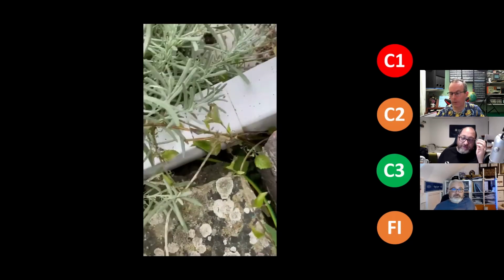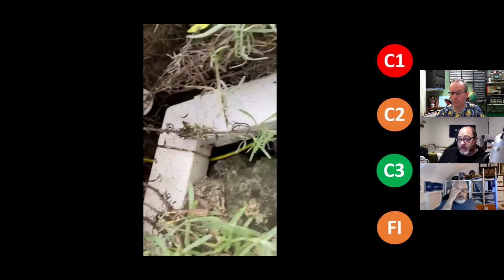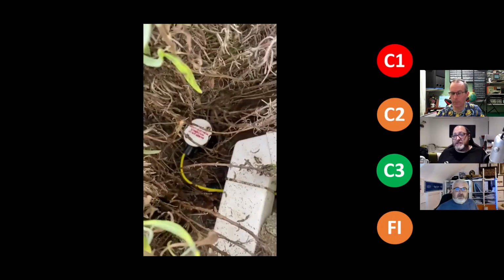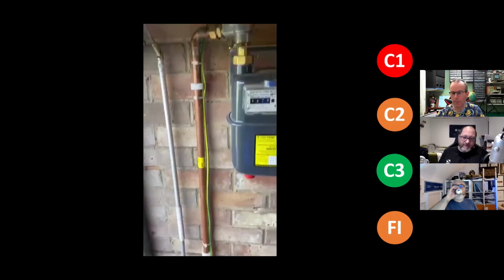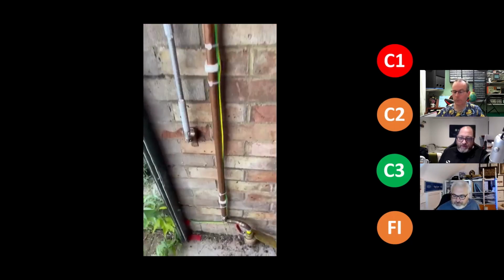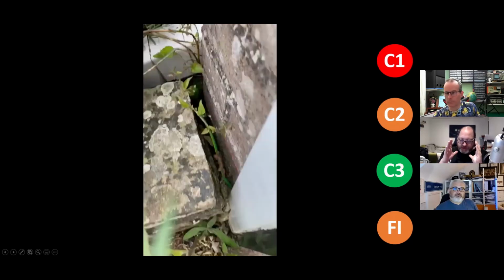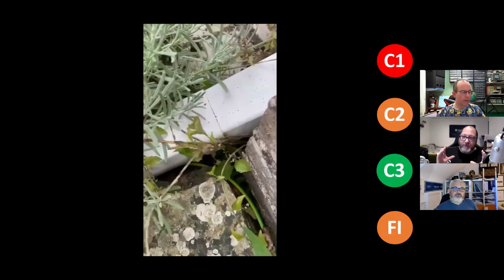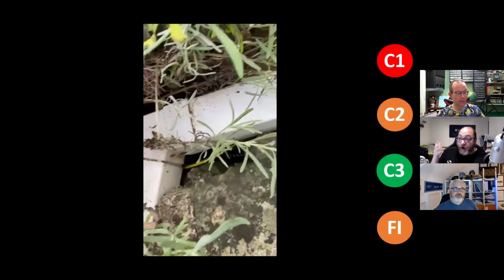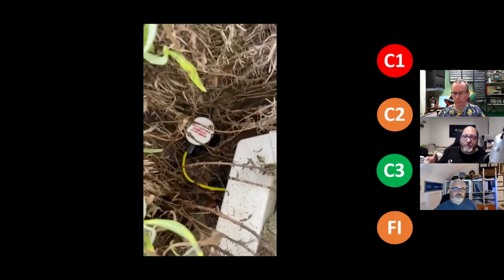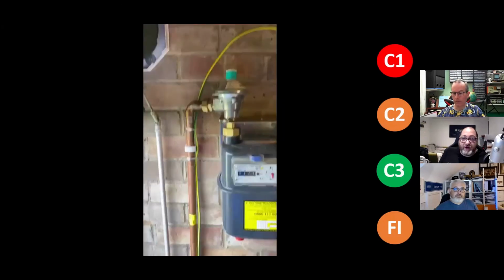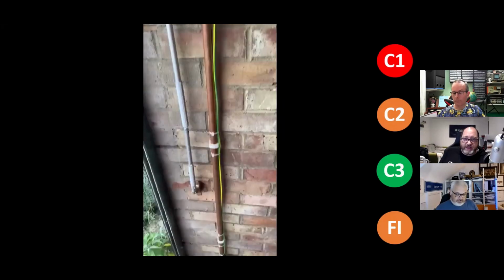If this is legit and not a bullseye, which I suspect it probably is, there's a lack of mechanical protection on that conductor out there anyway. But if this is carried out, we should have a paragraph of information informing electricians of that deviation from the norm, so they don't scratch their heads looking at it going, oh, this looks like it's a cock up.